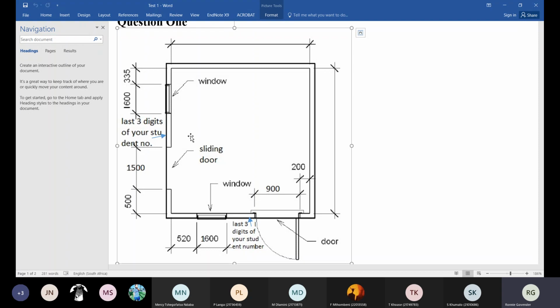And then the windows, same story. I'm going to add the 2 windows, the same height they are. So 1.6 is 3.2 meters, and it was 1.2 meters high. So I'm going to say 1.2 divided by 0.255, which gives me actually 4 courses. So it's 4 times 3.2, 4 times 3.2.